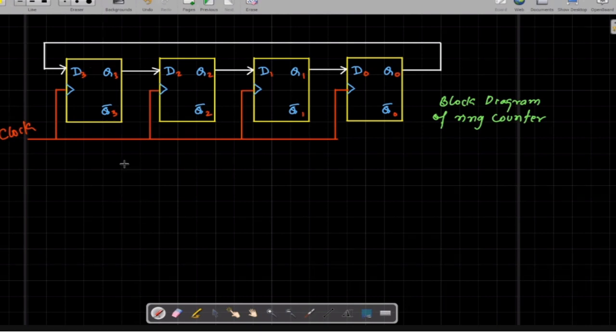So we first write the clock input, then we have to think of what is the individual output of these flip-flops. As I told you, you have to input only once using the preset input terminal of the first flip-flop, then it will start generating a shifting kind of one, and there will be only one flip-flop output at any instant of time.